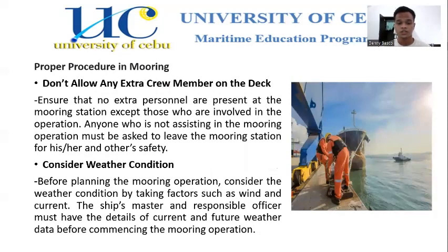First, don't allow any extra crew member on the deck. Ensure that no extra personnel are present at the mooring station, except those who are involved in the operation. Anyone who is not assisting in the mooring operation must be asked to leave the mooring station for his or her own and others' safety.